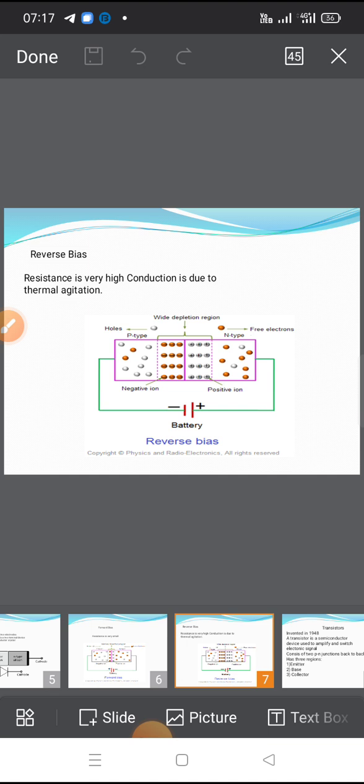When reverse bias is given to a diode, a very small current flows through it. This current is due to the movement of the minority carriers of charge. When the reverse bias voltage is increased, the kinetic energy of the electrons also increases. When these electrons collide with a crystal atom, they may knock out an electron from the covalent bonds of the semiconductor material. In this process, the covalent bond is broken and a pair of an electron and a hole is generated. Thus, one electron on collision with a crystal atom generates a pair of an electron and a hole.